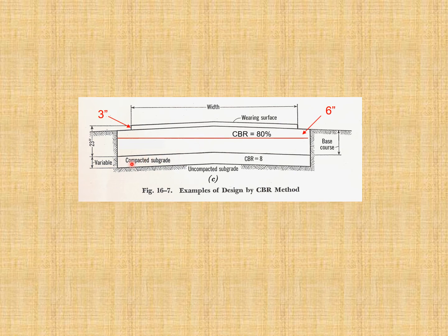So you can see that this is the subgrade. Above the subgrade, we are considering this as the base. Normally in the CBR method, we use the term base course, which is provided directly above the subgrade. But we are going to provide the base course in layers. The topmost layer has the best base material, and below that we will have relatively inferior base material. So we just want to know the CBR for this thickness of the base.